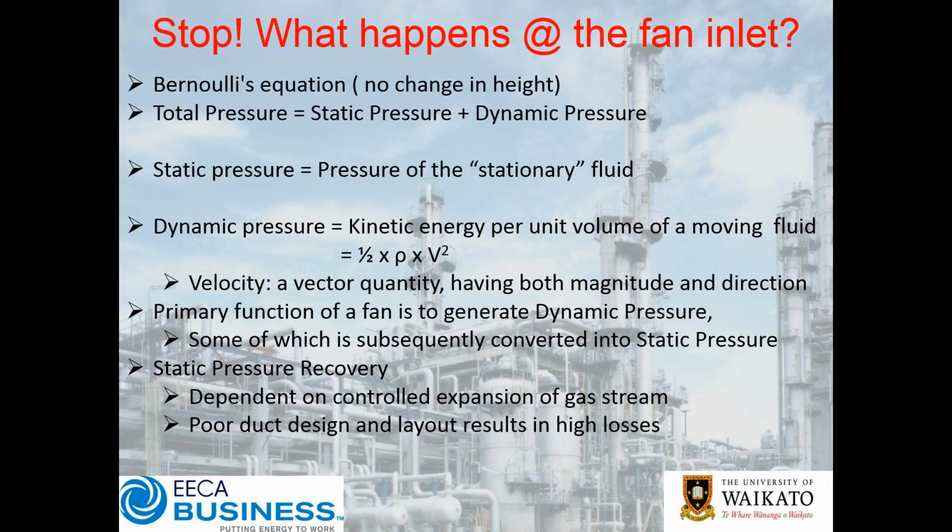And so this is where, especially at the end of a fan coming out the outlet, you can have a higher kinetic energy in the flow, and how we recover that, if we recover it and get that converted to static pressure, then that's a good efficient system. If we don't recover it that well, that can all get dissipated in turbulence and mixing, and ultimately result in inefficiency.